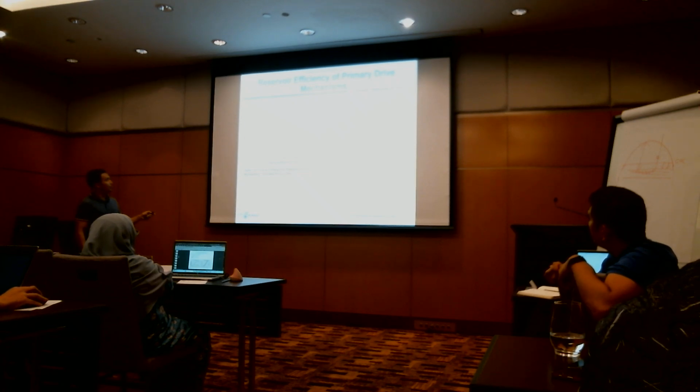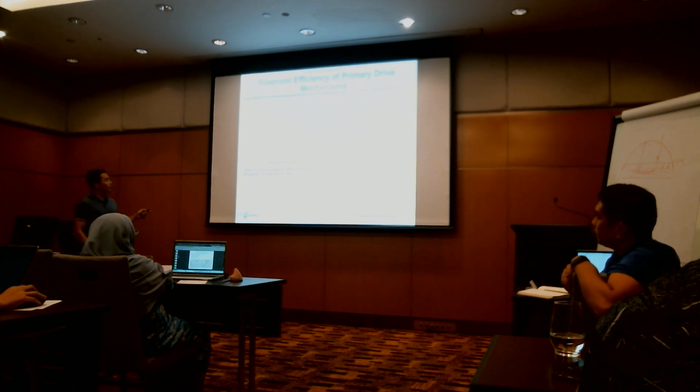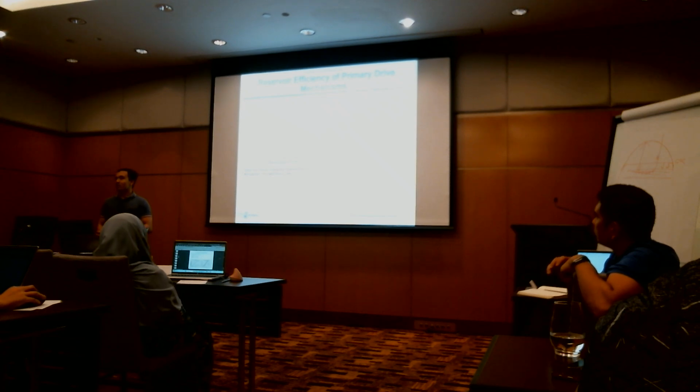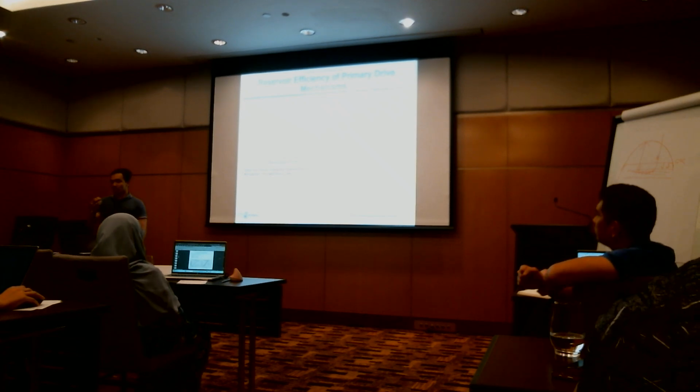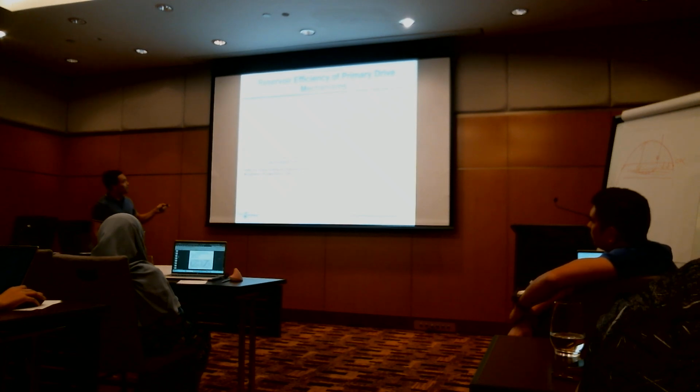Earlier, maybe we just talked briefly about this liquid rock expansion, but in the case that you have very limited solution gas drive, for example very heavy oil, it means that the gas inside your solution will be minimal. So that one will be purely governed by the rock or fluid expansion. That will give the lowest recovery, in this case less than 5%.